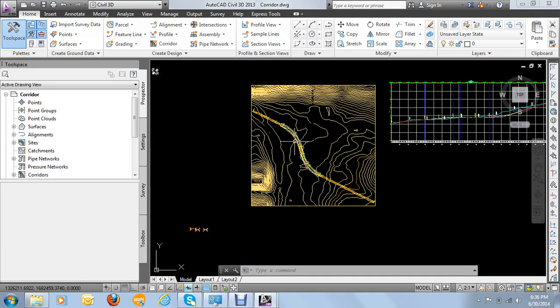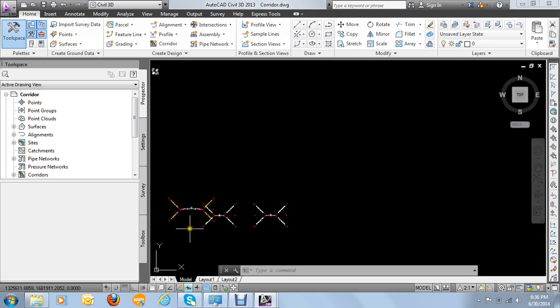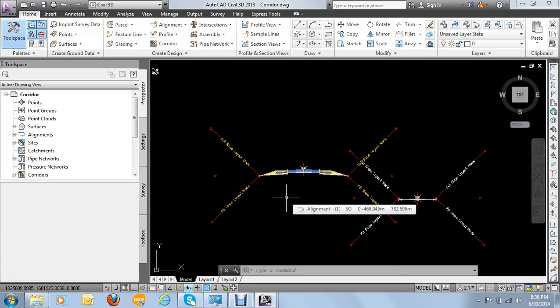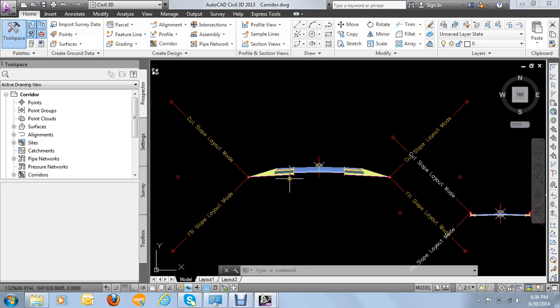The sections of the road that have drainage ditches, on both sides or one side, it depends on the total area. When you are doing the assemblies, you put that into consideration, whether you're going to put the ditches on either side or one. When you have a ditch, maybe after a lane, you just create it from the assembly.